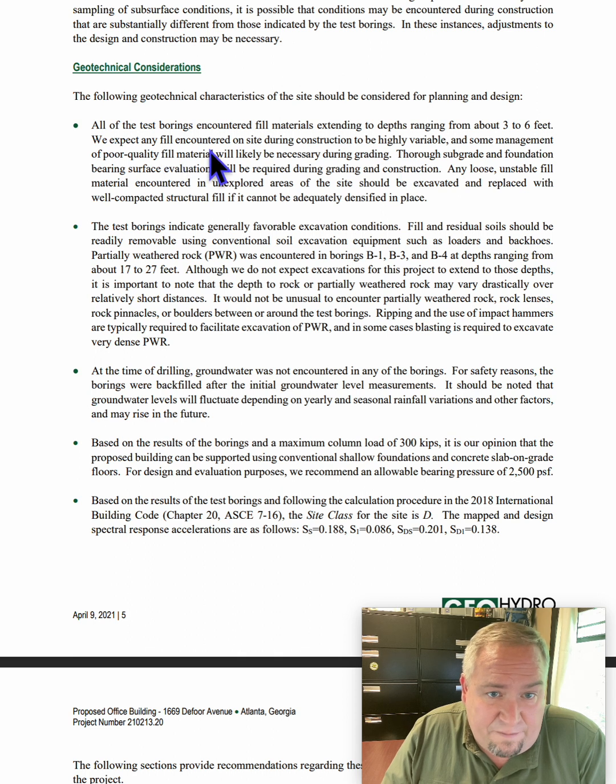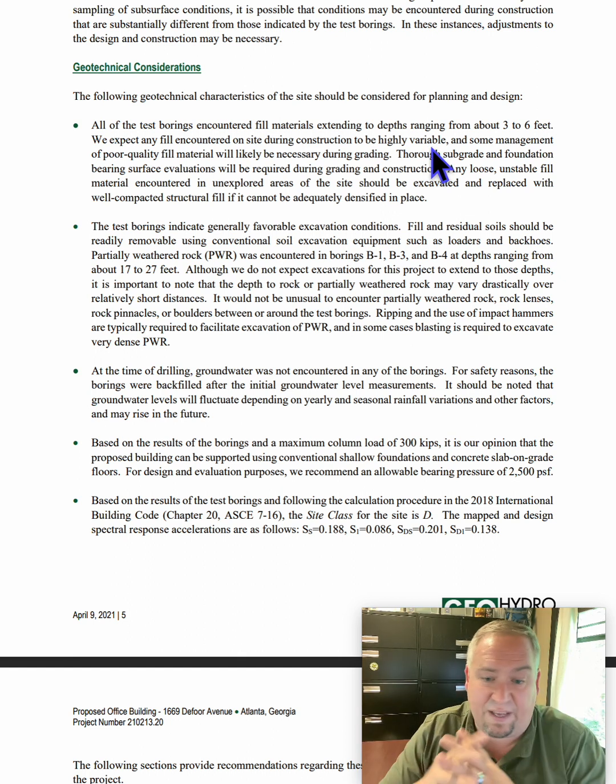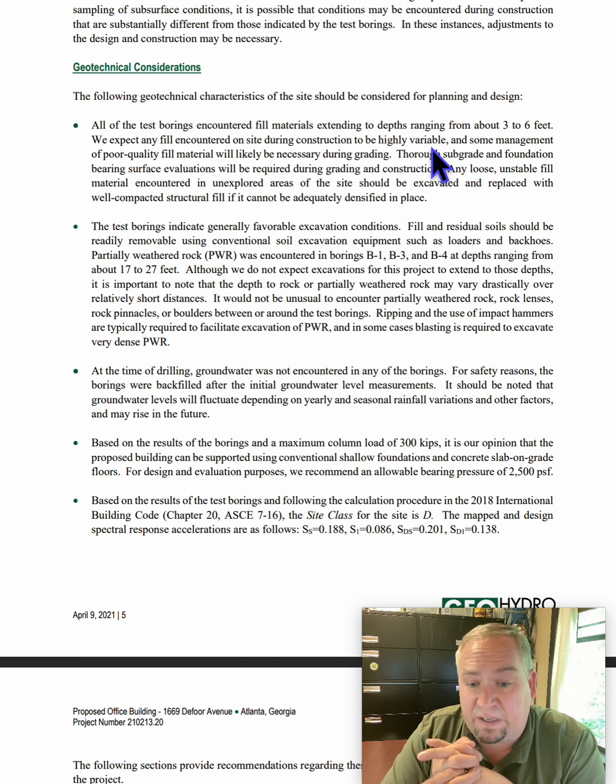We expect any fill encountered on the site during construction to be highly variable. So they're already telling you, guys, go ahead and tell the customer, we don't know what's down here. Let them know. And some management of poor quality fill material will likely be necessary during grading. I can already tell you, that tells you right there in the pre-con, before we even start the job, we're having our meeting, the geotech needs to be there. And when we start hitting in this section, they're going to be monitoring it.